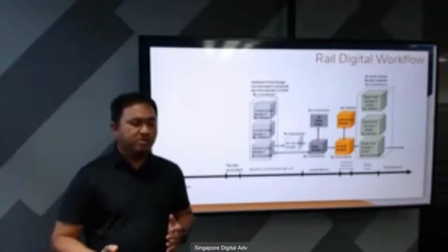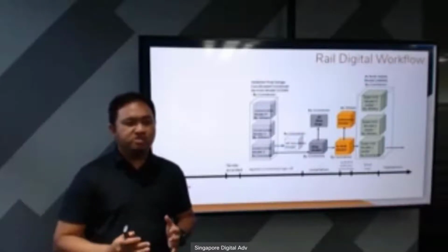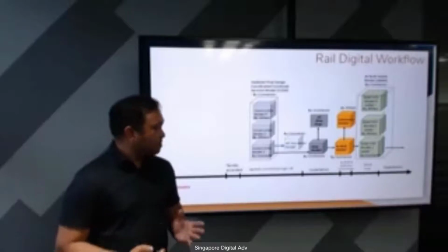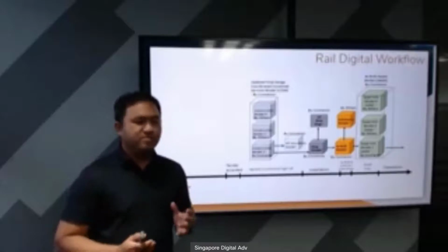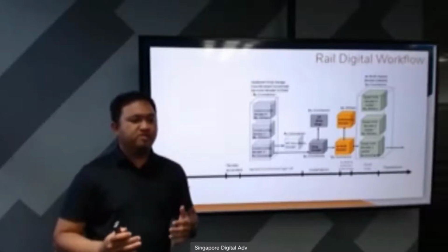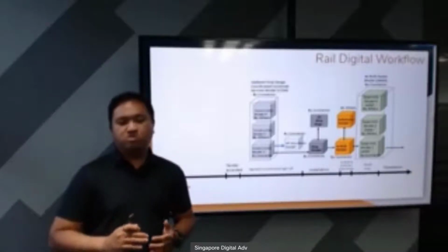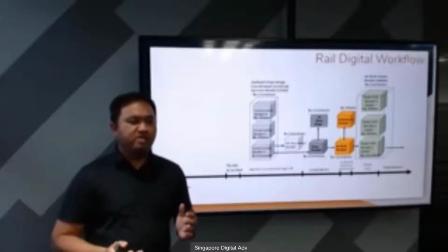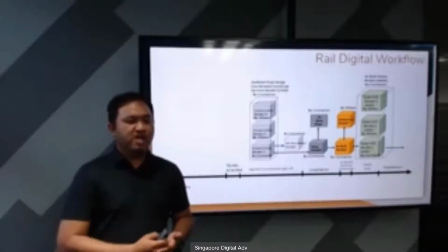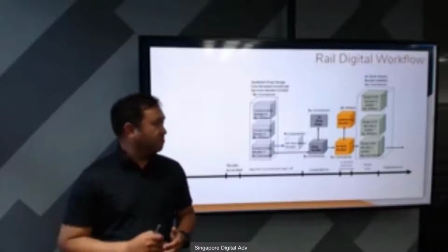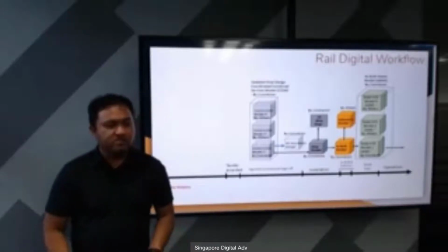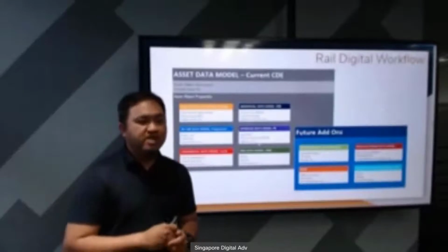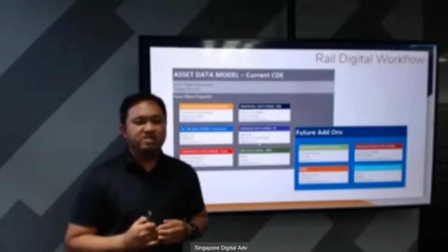Okay. And they're upgraded, versioned up, to become shop models. These are basically models that generate your fabrication drawings or your shop drawings. And this project information model becomes your as-built model. And the as-built model, if you populate it with 6D attributes, becomes a model fit for an asset information model. So they are upgraded from a project information model, from design all the way until construction, and then they become asset information models. In this case, it's actually termed the built asset model by the contractor, but it's given to the client.